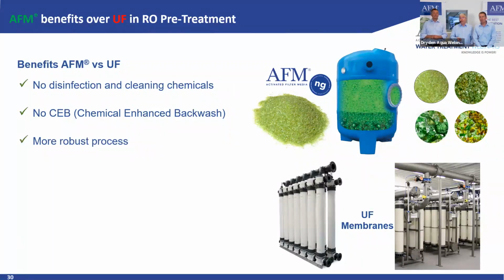So consequently, our system with AFM is much more robust because we are more able to take bigger peaks of load, which may not be really good for UF. Peaks are never nice, we also like to have it constant. But if there are peaks in turbidity, etc., it's normal and easier to compensate for. With the UF, it's more difficult. It's much tougher. Yes, exactly.